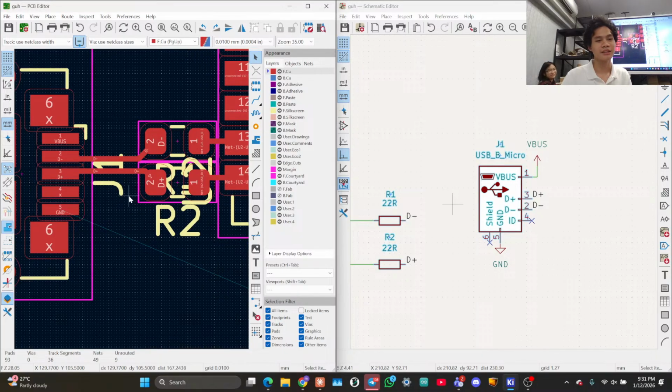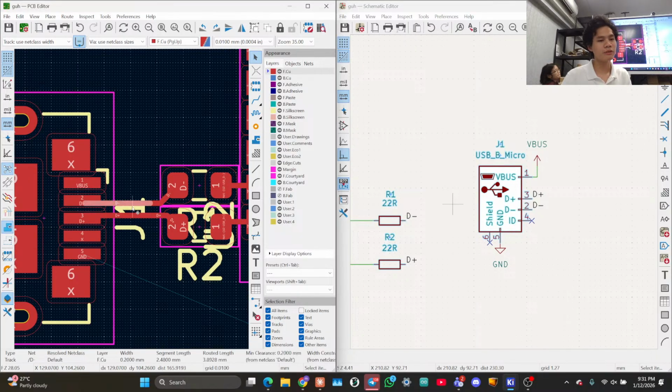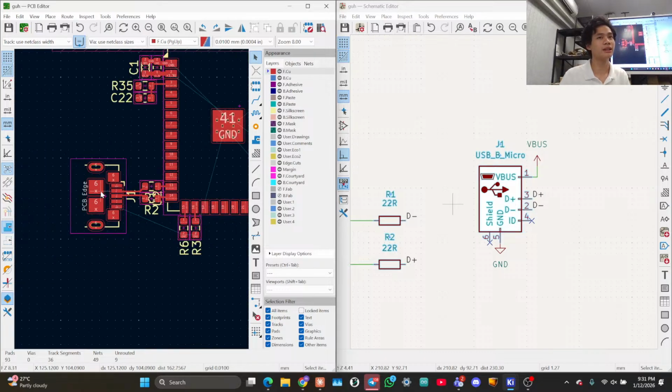Okay, great. So you need to route it as a differential pair basically, alright? And if you make this really long, then stuff will start breaking because it absorbs too much interference from like the universe. So don't make your USB longer than it needs to be, you know?